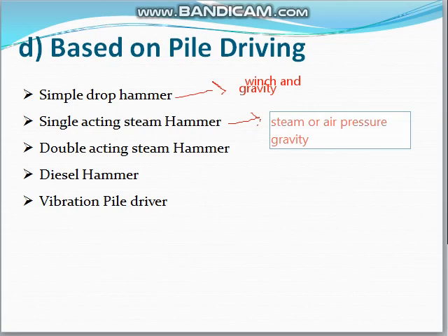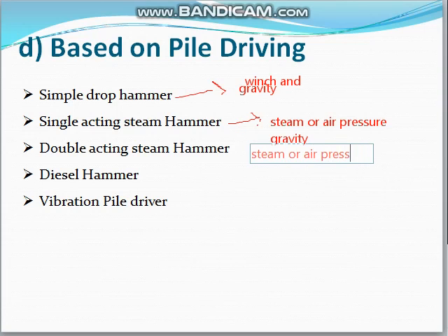So this is about the single acting steam hammer, and now the double acting steam hammer. Here also the hammer is raised by steam or air pressure, and steam or air pressure is also used to push down the hammer.